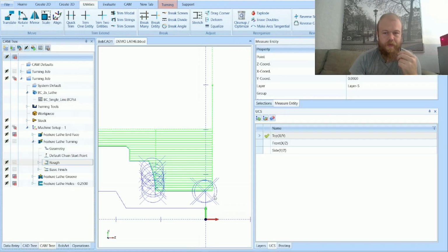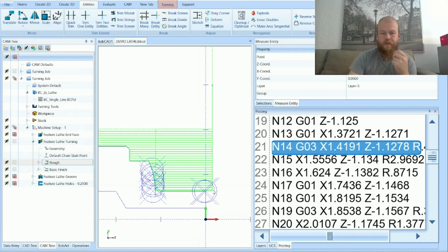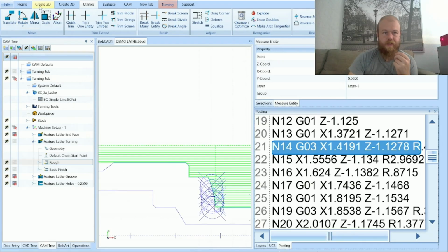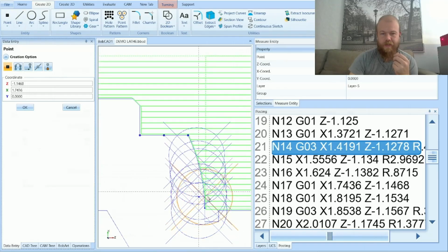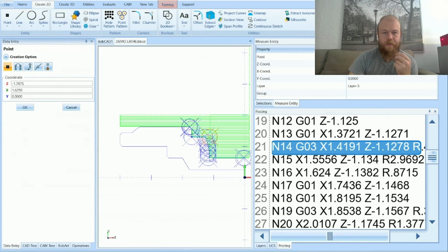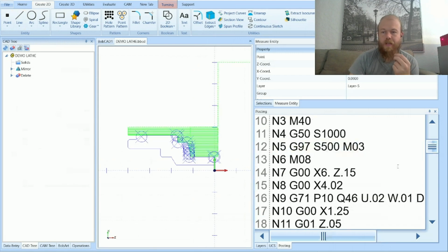basically this G code in the can cycle is going to be plotting the points of the profile, as I mentioned, and just for the sake of time, it's giving us a lot of points for this arc. It's going to get to this arc, come over here, come across. It's going to plot all of these points for us. So it's telling us this is the profile, and just at